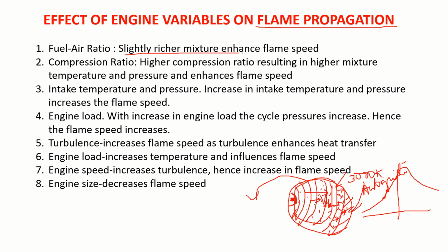So a slightly rich mixture enhances flame speed. If you have a high compression ratio, high mixture temperature and pressure, that enhances flame speed. If the intake temperature and pressure increase, flame speed increases. But note that in the meantime, these factors reduce the ignition lag too.